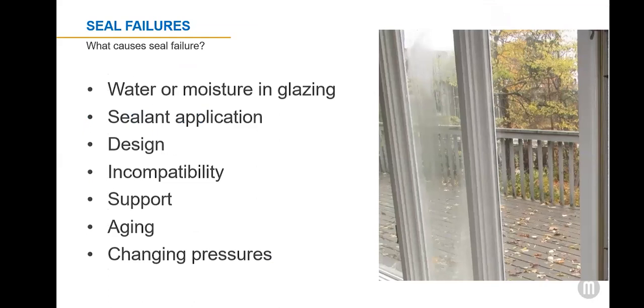Conditions that cause insulating glass failures. An IGU seal can fail when the desiccant used to keep the space dry no longer absorbs moisture that migrates. This can happen because of natural aging or because of unsatisfactory design that allows moisture to become trapped near the edges of the IGU. Other issues can be skips or voids in the sealant, incompatible glazing materials with the sealant. Adhesion of the sealant to the glass could fail, elevation changes without proper ventilation, and also natural aging, temperature, pressure, humidity, and UV exposure.